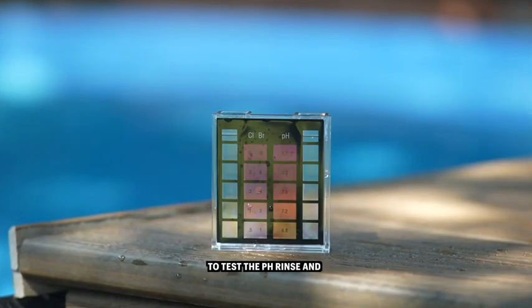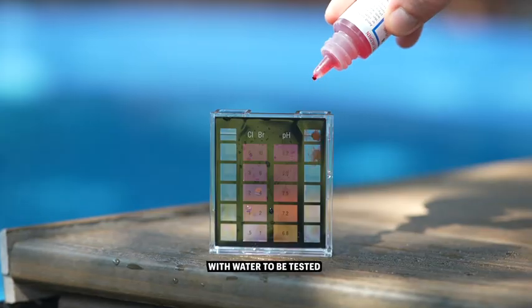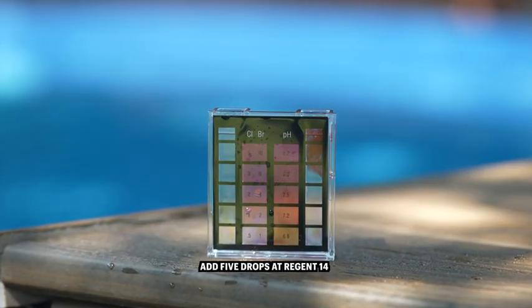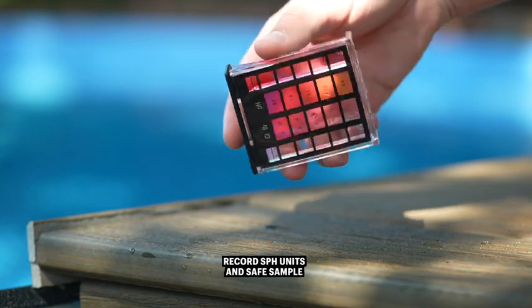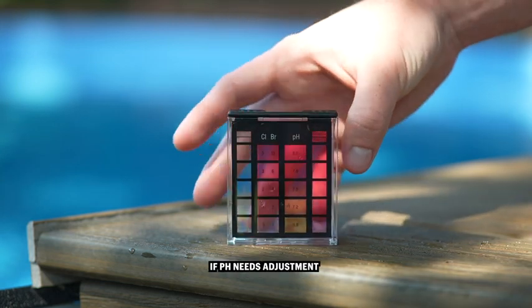To test the pH, rinse and fill the pH cell to the mark with the water to be tested. Add 5 drops of reagent 14, cap and invert to mix. Match color with the color standard. Record as pH units and save the sample if pH needs adjustments.